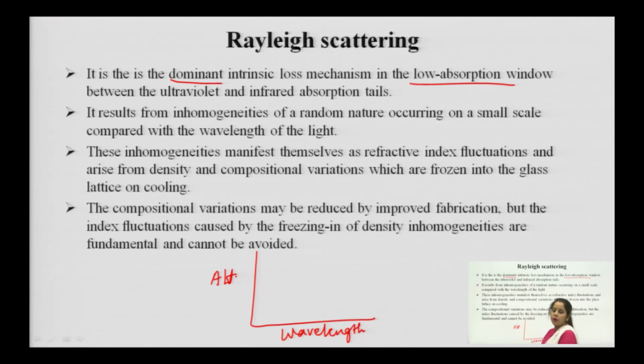There exists a relationship between attenuation and wavelength. It is not possible that in each wavelength there will be equal attenuation. Attenuation varies as per the wavelength. In some wavelengths attenuation will be greater, and in some wavelengths attenuation will be minimum. So, we always have to make optical propagation possible only in that window of wavelength where there is low attenuation.